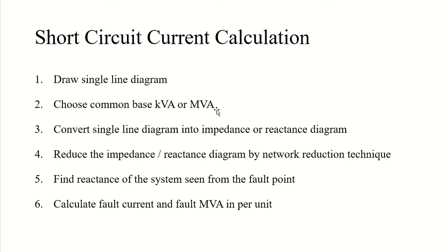Reactance is in series, because the resistance of your transformer will be very low compared to its reactance. So we basically ignore the resistance, and the shunt elements of the transformer will also be neglected in this case. Then the resistances of your whole system will also be neglected. Only the inductive values will be considered, which means basically inductive reactances.